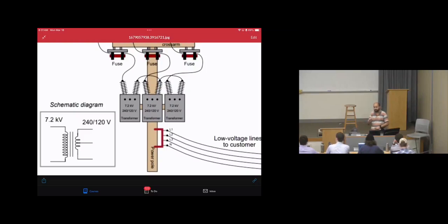A small percentage of unbalance can be allowed, up to 3%. Sometimes it can be violated up to 5%. If there is more than 5% unbalance, then we need to take action. We can make some studies and say maybe phase C has lower loads than the others, then we can connect an additional home to maintain the balance. So, overall, to overcome some problems in the power utility, we are trying our best to make it as balanced as possible.